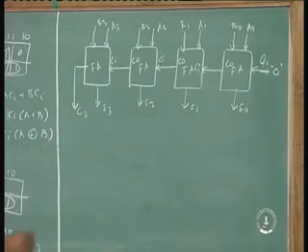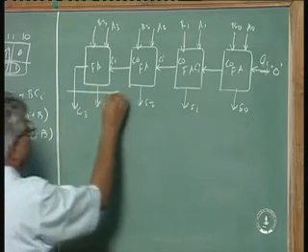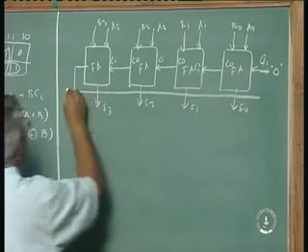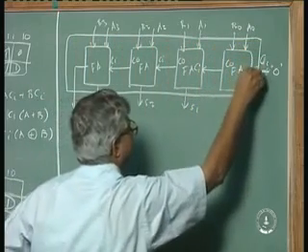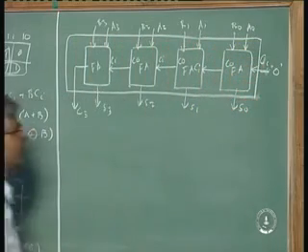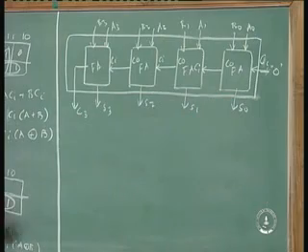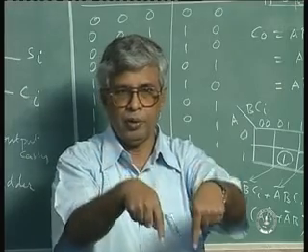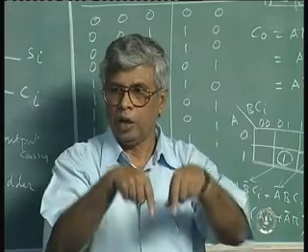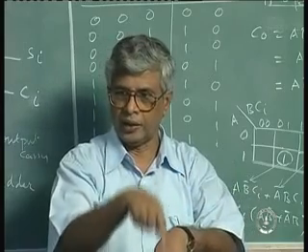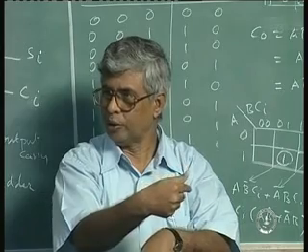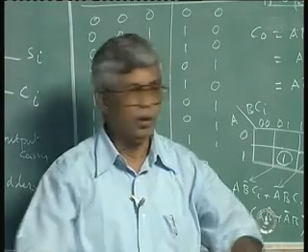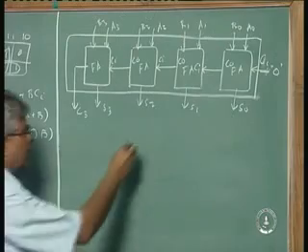The whole thing is called, so when you are going to the shop to buy a 4-bit adder, you have only these A's and B's to be fed in. A0, B0, A1, B1, A2, B2, A3, B3. Out comes S0, S1, S2, S3 and C3, and you have to give the C in as the input, as 0. This is called a 4-bit full adder.